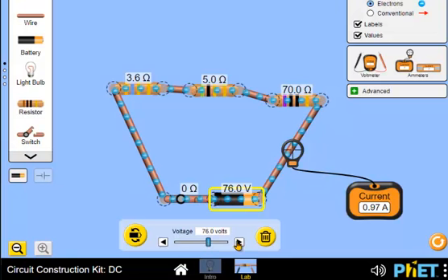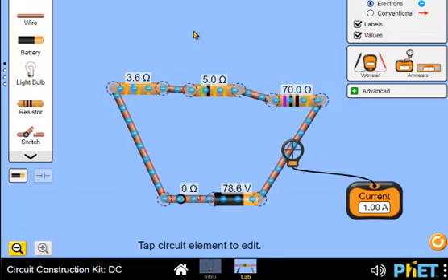Okay, so I'm going to get up to here, they're really close. There we go, 1 amp. So here I have now 78.2 volts divided by 1 amp. Ohm's law gives 78.2 ohms, but because I've shifted the decimal point, it's 782 ohms, which is, within rounding, the same as the 786 that I had earlier. By the way, if I push this up a little bit, notice that there's my 78.6, right? Shift the decimal point, and my current didn't change. That's because of sig figs. Okay, that's a series circuit.